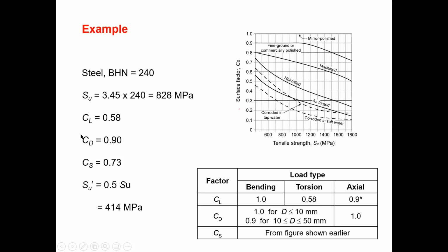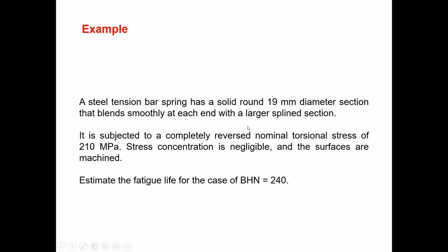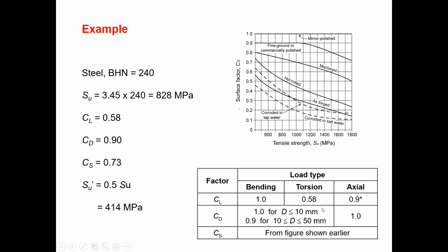and the dimension they provide in here is 19 millimeter diameter. So it is higher than 10 millimeter. If it is torsional load, CD is 0.9. Okay, and CS, the surface factor. So for that, the ultimate stress you already know.